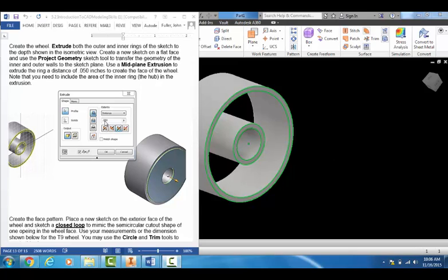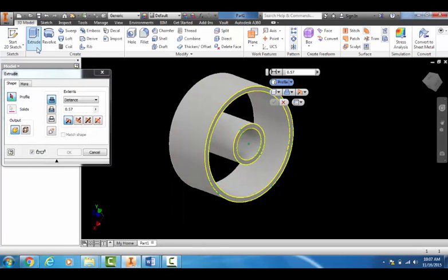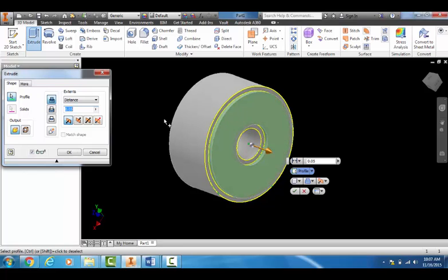Looking back at our assignment real quick, we need to extrude this inner piece 0.05 inches. But we need to use this button right here. This will move it inwards, and it will also move it outwards, 0.05 inches. So let's come to our extrude button. Enter 0.05 and click on that surface. We want that one because we want it to go inwards too, and also outwards, both directions, and hit OK.